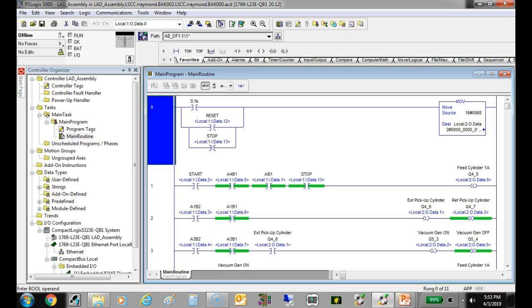This is the primary language that we use to program PLCs, ladder. Why? Because there's a lot of people that understand it, and it makes sense, especially people that have come up through the electrical trade. And these right here, these are not actually coils. These are the symbols for coils. For some reason, Allen Bradley puts it inside of, I guess they did it because when they originally drew it, all you had was what was on the keyboard on the computers that they did it. Allen Bradley's been around for a long time.